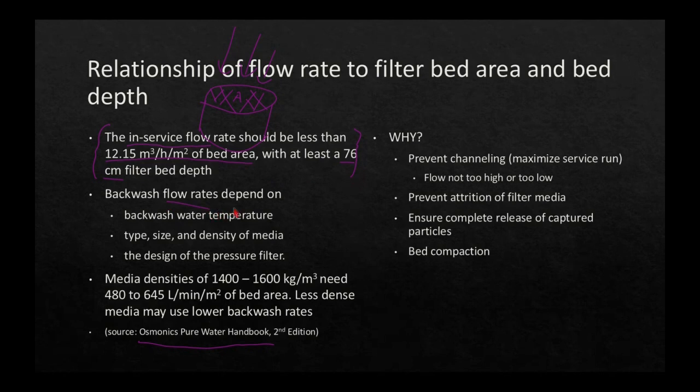As for flow rates, how much backwash depends upon backwash water temperature and the type, size, and density of the media. So ultimately, you're reading up and it says the backwash flow rate should be X, and you're going, why? Oh, because it's designed that way.